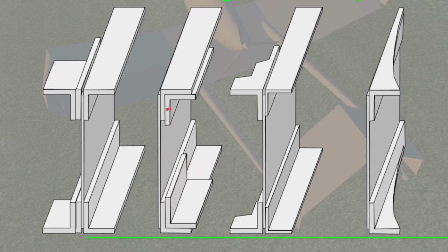And then here's another way of doing it. In this case, there's only 2 steps, but you could double up your angles. That's another way of doing it. Although this is a little bit more difficult, generally because the cross-section area of these angles has a rounded corner on the inside corner, which means on this inner angle, you would actually have to remove some of this sharp corner so that it would fit comfortably in there and make good contact with both faces on both of these angles.